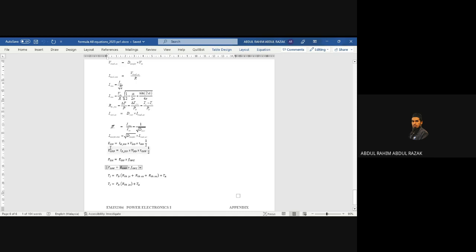How much depends on your drain current: I drain current times your VDD maximum times your T on, divided by 2. So this is the amount of area below your switching on and off triangular waveform.